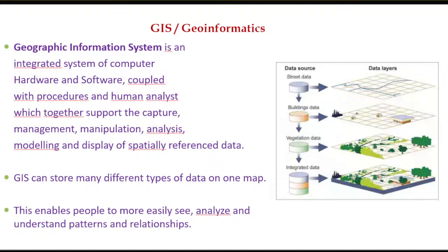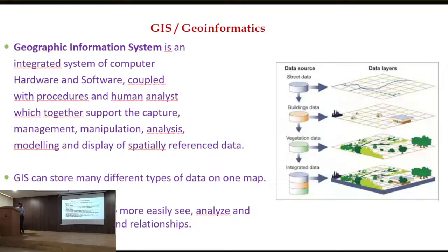There are two types. One is the raster type, which is called an image. The second one is the vector type. The vector type has three types of features: discrete points, lines and polygons, whereas the raster is regularly spaced grid cells in a specific sequence.